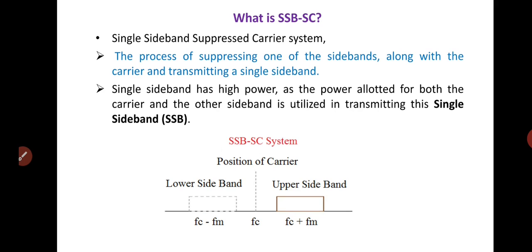We have derived the expression that the carrier contains 2/3 of the total power and contains no information. So we can say that amplitude modulation is an inefficient method of communication, since 2/3 of the transmitted power is wasted. The actual information is within the sidebands. And the efficiency of amplitude modulation can be increased by removing or suppressing the carrier before it is coupled to the antenna for transmission.